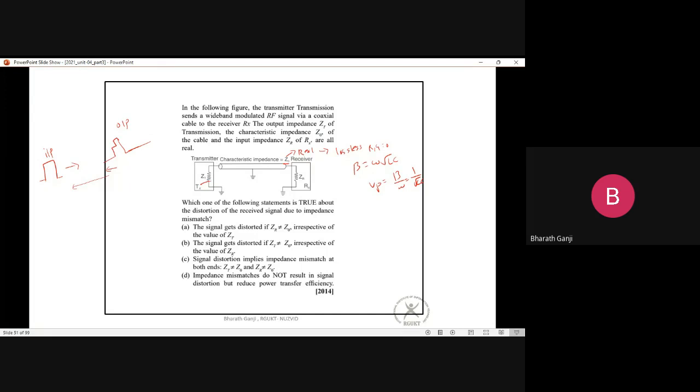on the line. But what is the problem here is, when the impedances are not matched, the reflected wave can come back, and the overall resultant pulse which you receive here might not have the same shape which you are expecting, right? So that kind of distortion can happen when you're dealing with pulses, or signals with many frequency components, but you cannot look into it when you're dealing with only sinusoidal analysis.